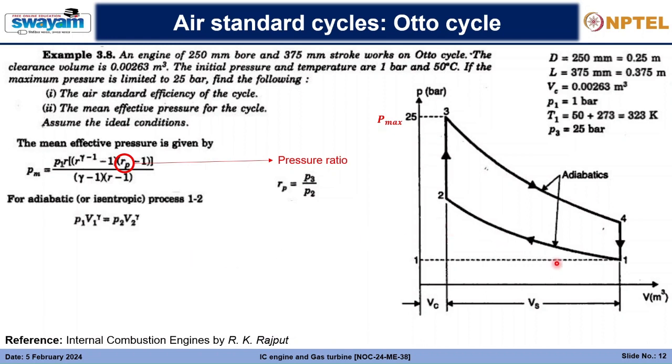Why have we considered this first? Because we know the starting condition, P1 and T1, right? So extrapolating from here to point 2 and then from point 2 to point 3, we'll finally get all the values of P3 and P2. If we use the thermodynamic relationship of an adiabatic process, this is what we will get, and solving it, we will get 18.38 bar.